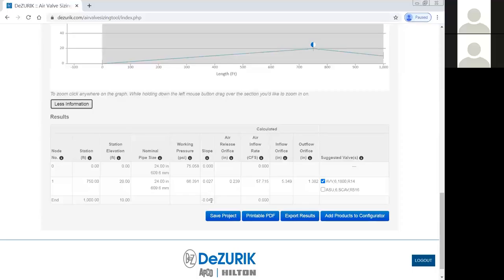The air vac valve sizing is based on the greater of the two, the greater of the absolute value of either one of those, which is the 0.04 in this case. So it figured out the air vac valve has to be 6-inch. And what it also tells you, though, air vac, of course, is inflow. The vacuum protection is inflow. So it says there's about 57 cubic feet per second of inflow. And translate that to what size orifice would that be? Well, that's 5.349 inches diameter orifice. Well, we don't have a valve that size, but we have a 6-inch, so we default to the first valve bigger.